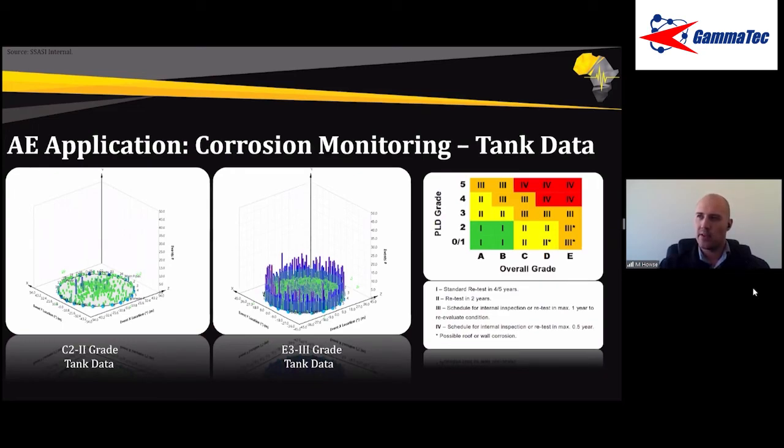So if you're comparing it to the minimum size crack found in a material, UT phased array would detect all cracks, where acoustic emission would detect the active ones. And depending on how dense your sensor array is, how many sensors we have on there, we can get just the same amount of sensitivity as UT. I mean, if you have a crack happening directly under a sensor or just an inch away, you definitely detect it, no matter how small it is.